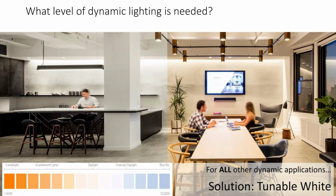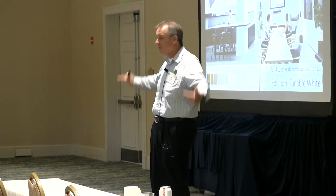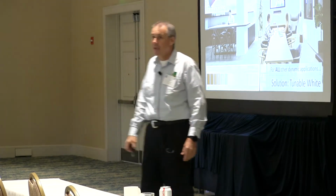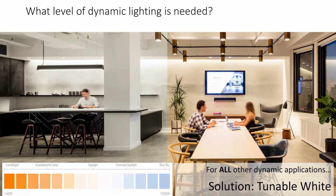And this is typically how it's done with tunable white. There's typically two LEDs or two LED arrays in the fixture, one at a cool color temperature, one at a warm color temperature, and you just change the ratio of intensity of each. How you change that intensity is a bit of a trick, but in theory, you just drive one more than the other and you can get anywhere along that straight line.